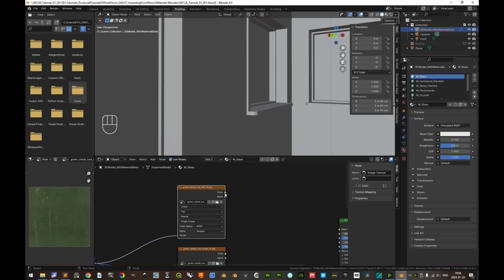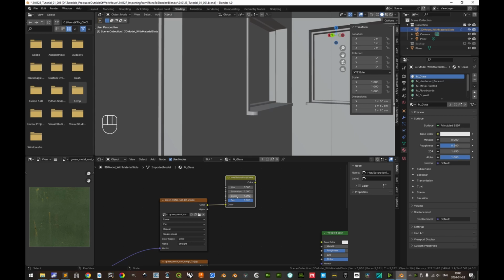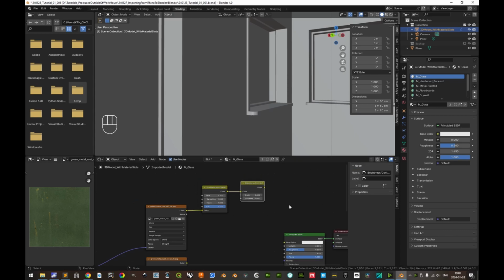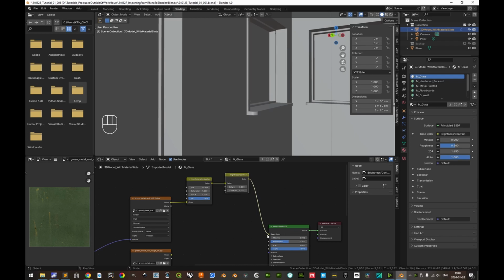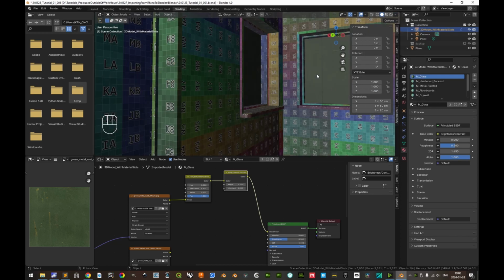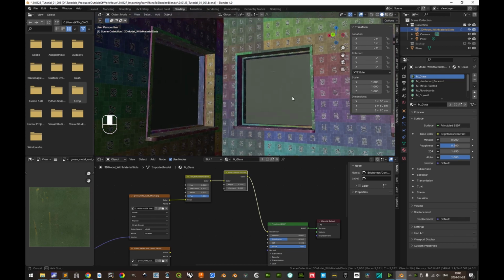The base color or diffuse or albedo, it should have a hue saturation value node here. And this of course is not the hue input, but this is the color input. So as to be able to easily change the saturation value. And this can be complemented with a contrast. And here we make sure that the input is the color input. Very good. This should be our base color. Now this should be reflected in the viewport, or we can change from material to texture. And we see here that we have the base color texture here as our template material.